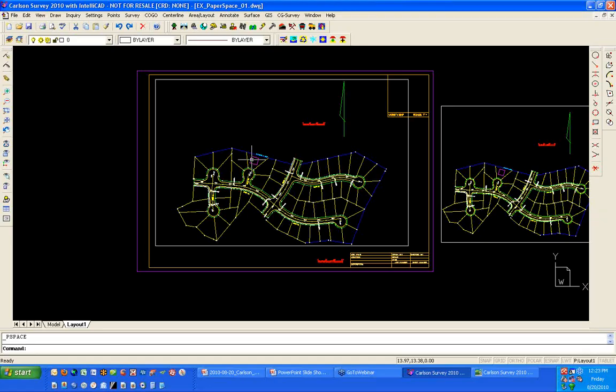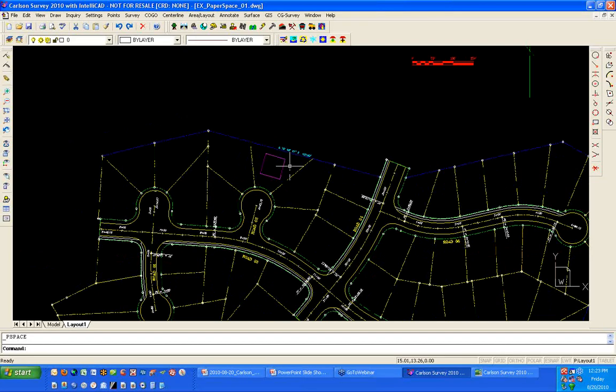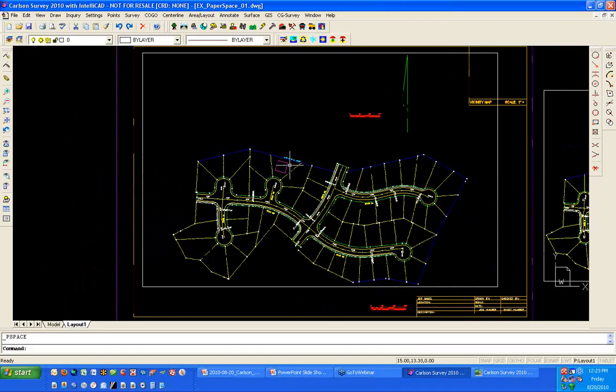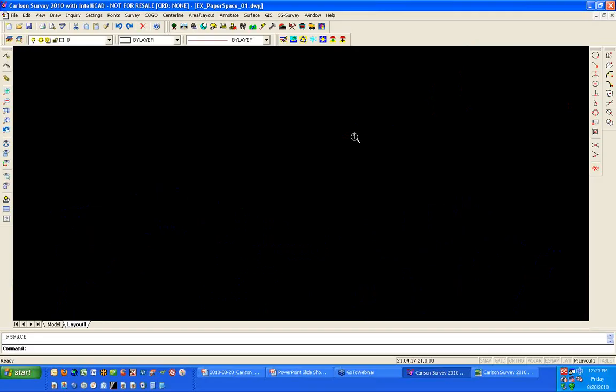So if the view that we have on here right now is at 50 scale, then I should be able to measure between these 2 points, and it should come up to 1. It should be 1 inch, or 1 unit representing an inch. I should be able to measure between here and here and have that be 1 or an inch.